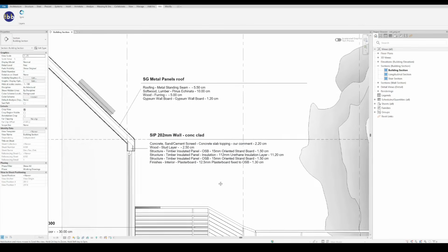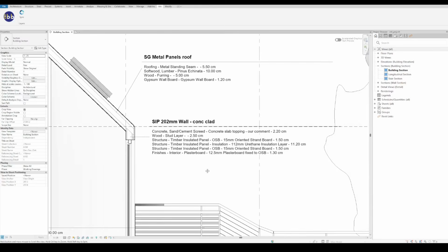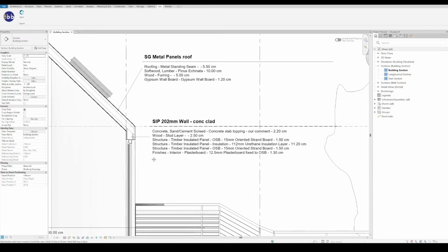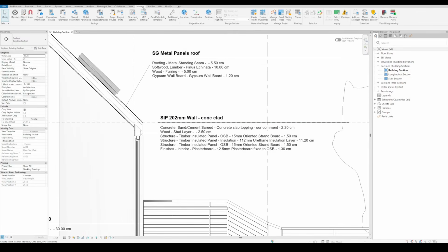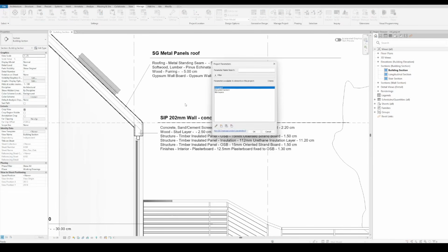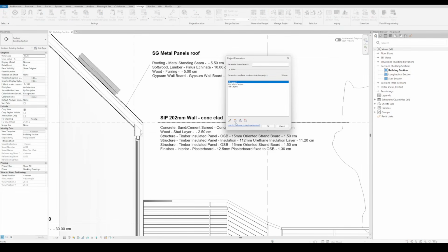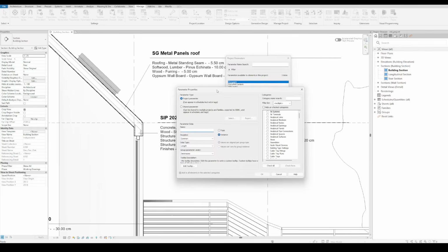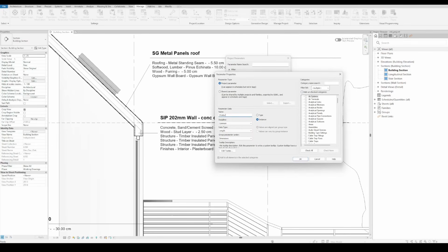And at the end, as I mentioned, let's add some custom parameter for us. I will do something simple. Let's go to the project parameters and add a product code parameter. Let's call it like that. Let's make it a parameter of type text. Of course, you can use any type available here.